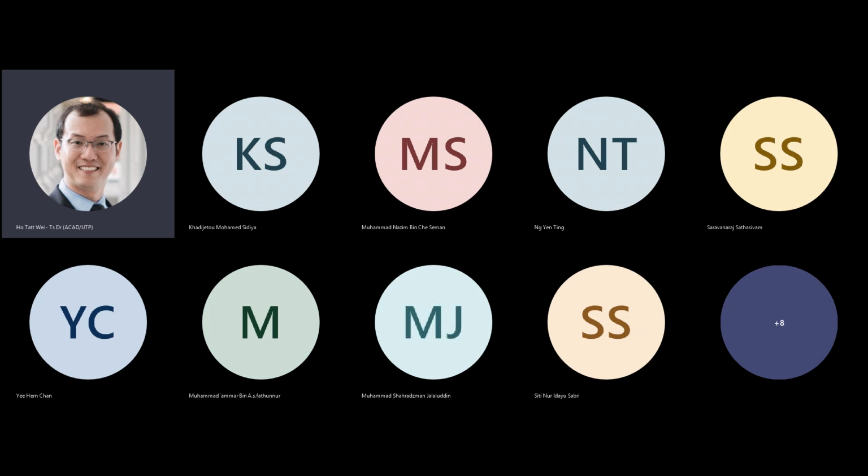It's going to be linear with the number of inputs here, whereas on this point here, it's probably also the same, but there are certain ways you could size this transistor. But this one is quite favored because it's a small and light implementation of it. But you have to be a bit careful, especially if you do multiple layers of multiplexer.